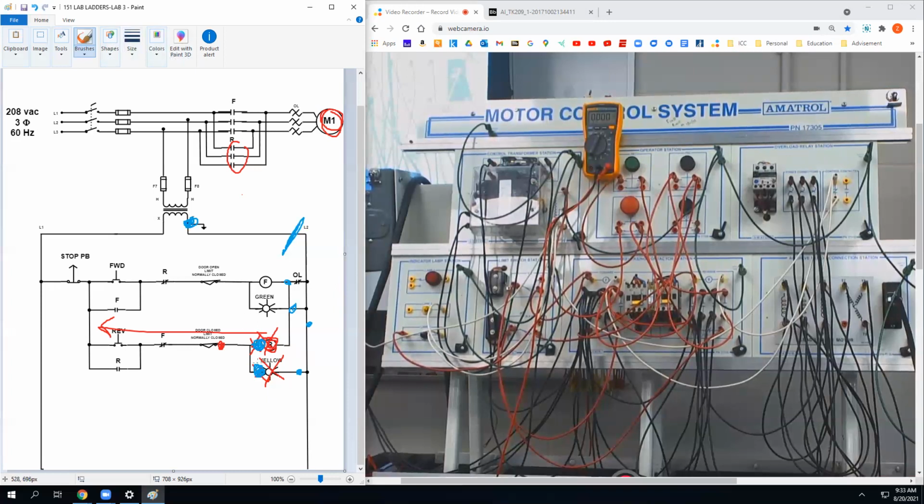All right, back to voltages. I got 0 volts, 0 volts. Where's the next place I'm looking? Heath said it already. You have 0 volts on the limit switch? Check the other side. 0 volts. And then I'm checking here. 0 volts, 0 volts, 120. Oh, look, on the line side, I got 120. What's the problem?